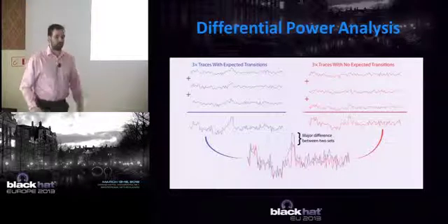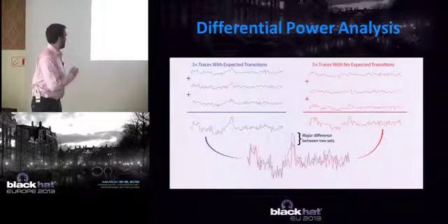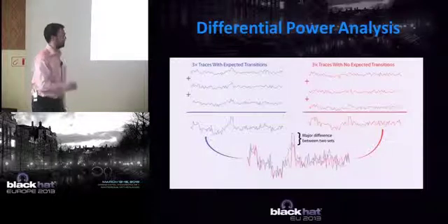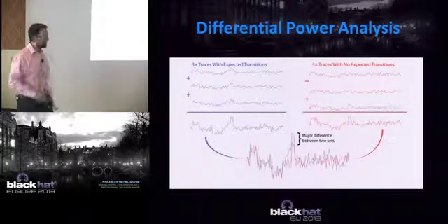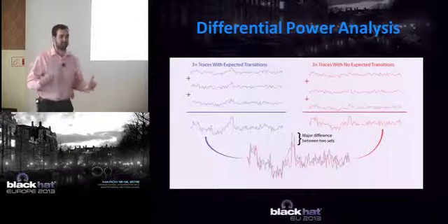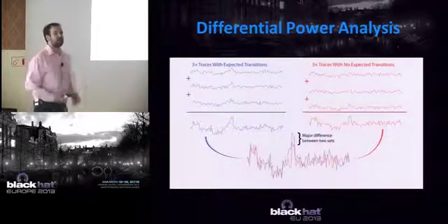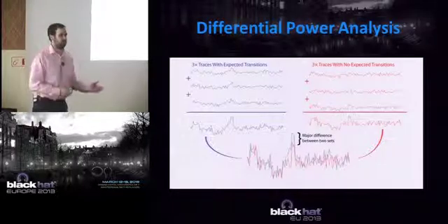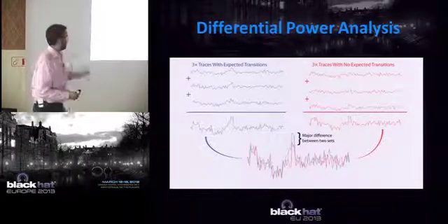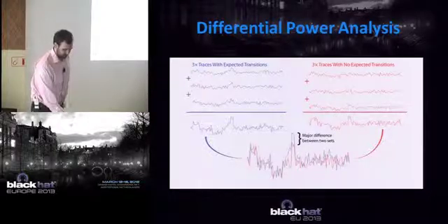And when I compare the average, or add up all of those sets I've made, I should see this difference. If I was wrong, and assuming you have a lot of traces, not just 7, it should just average out to 0.5, and the rest of the bits should also average out to 0.5. So this is how we do the original differential power analysis.